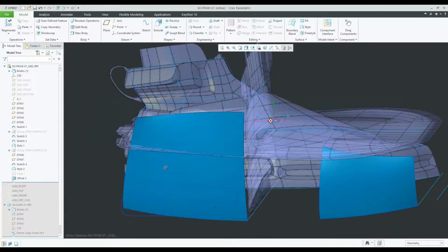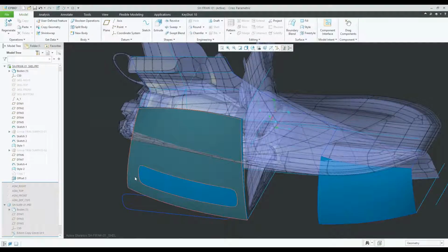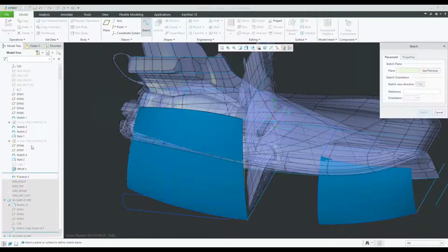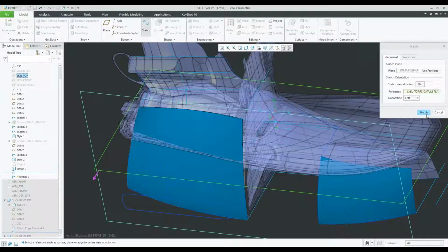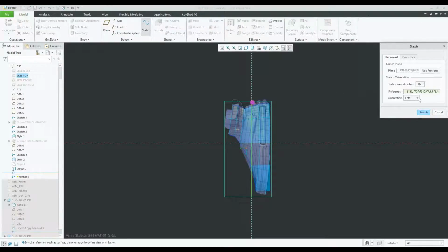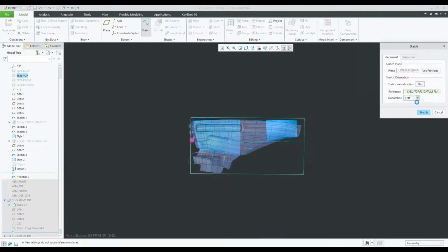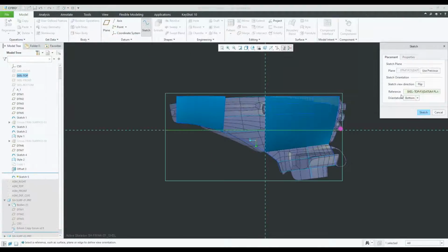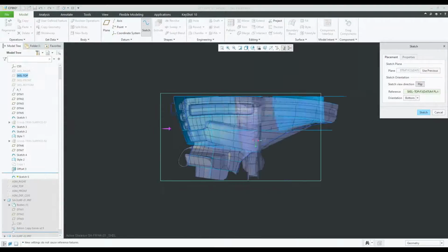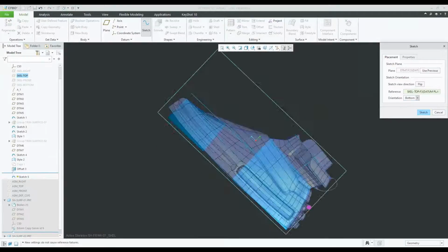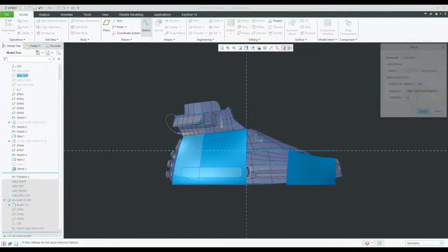All right, cool. So now we have this surface that was created in ISDX. We have another surface that we copied and offset. So I'm going to go and sketch on that datum 7 plane that we created. All right, click sketch, and I might have to go into sketch setup and adjust this a little bit. Here we go.